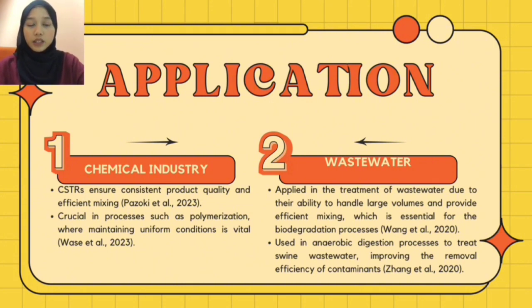CSTRs have stable and unstable equilibrium points, making temperature regulation difficult, especially in exothermic processes, where sudden temperature rises could affect product synthesis and reactor safety. Traditional proportional integral derivative (PID) controllers fail to regulate a continuous stirred tank reactor under variable operating circumstances due to their rigid parameters. To overcome the issue, a PID controller with fuzzy gain scheduling has been recommended.